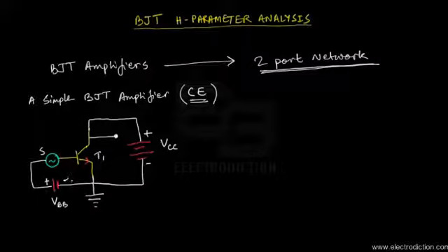We can see that due to this kind of setup, whenever the power to the circuit is turned on, you're going to obtain an input voltage across the base and emitter terminals over here. Let's call that Vin. And across the collector and the emitter you're going to obtain an output voltage known as VO or Vout, whichever way you might want to express it.